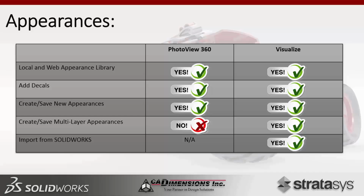Now, of course, the last topic here is import from SolidWorks. The appearances, of course, do import from PhotoView360 or from SolidWorks and come into Visualize. Obviously, this doesn't apply in PhotoView360 because you're already in SolidWorks, so that will carry over. But that's typically my workflow. We haven't gotten to workflow, but usually I will apply my appearances in SolidWorks and then just ship it over to Visualize.